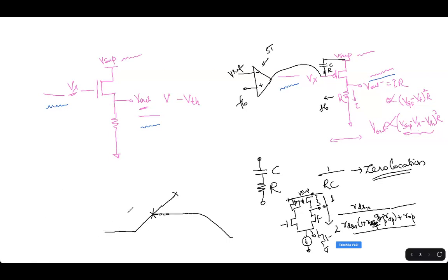On the other hand, let's say you plan to use a PMOS input based OTA. How will it look? The PMOS input based op-amp will look like this. Now, with a PMOS input pair, from VSUP to Vout there are two transistors.